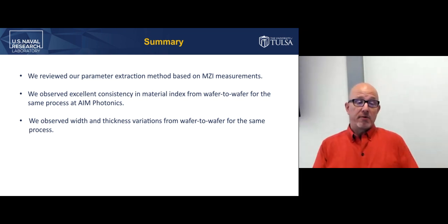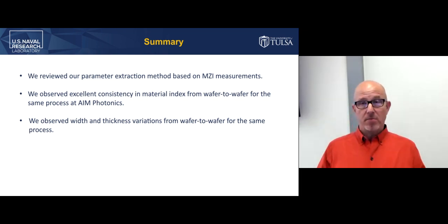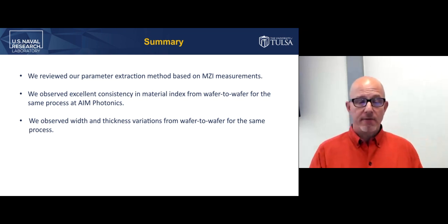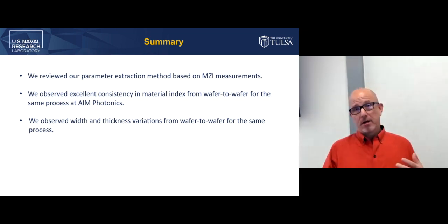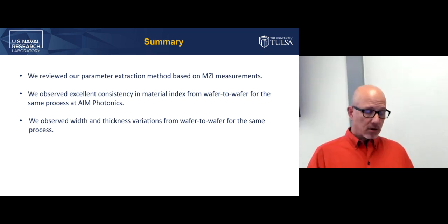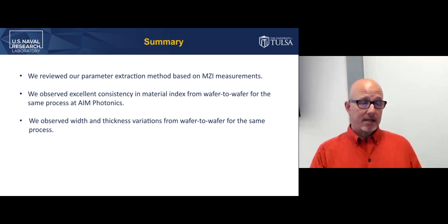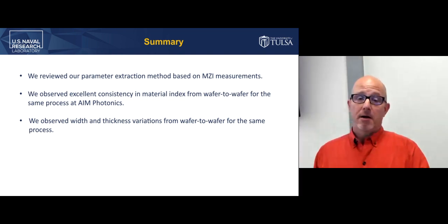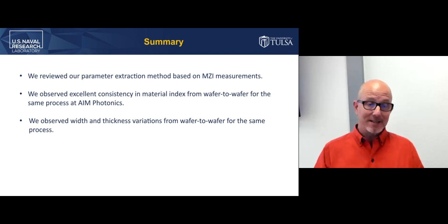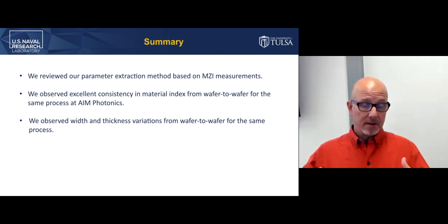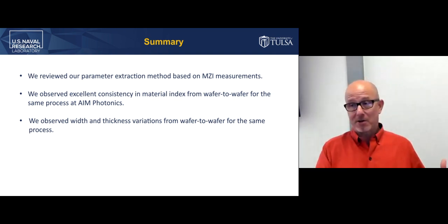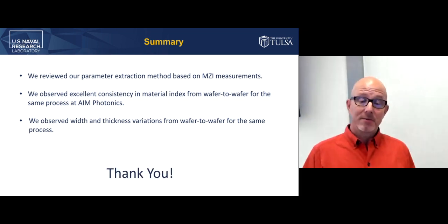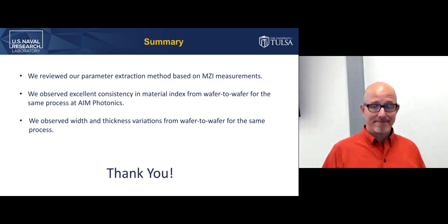In summary, I reviewed our parameter extraction method based on Mach-Zehnder interferometer measurements. We observed excellent consistency in material index from wafer to wafer in the same process at AIM Photonics, but also observed width and thickness variations as expected from wafer to wafer in the same process. So it's extremely valuable to get feedback to the foundry about this process, and that is really in its youth in creating photonic integrated circuits. So anyhow, we'll say that, and thank you very much for your attention.